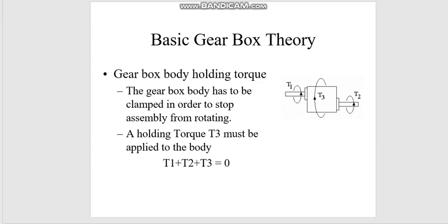So in designing the gear system, one of the elements that you need to be able to calculate is the gearbox body holding torque. If you imagine there is a torque applied at the input, there is a torque on the output of the shaft, and basically if nothing is holding the body of the gearbox, then this body will also rotate, right?